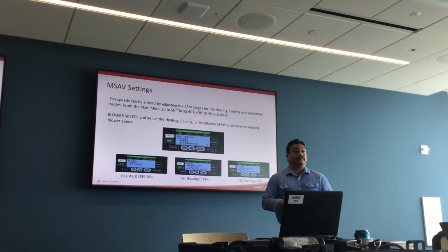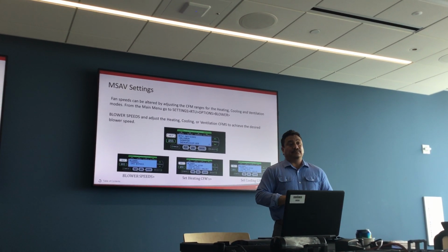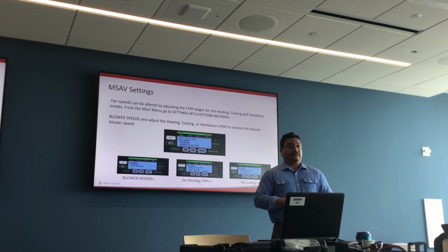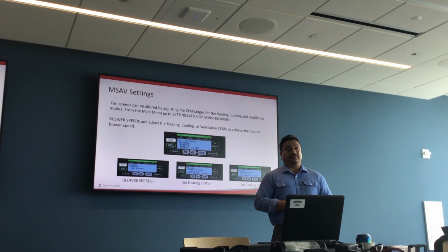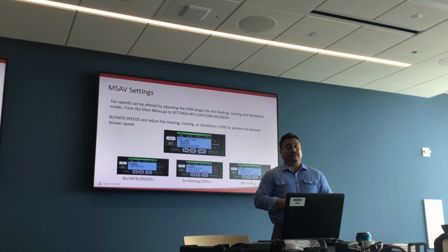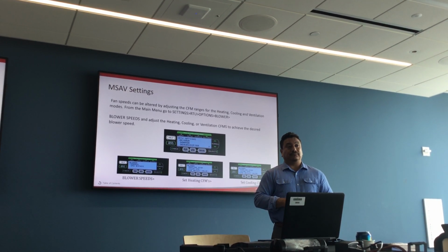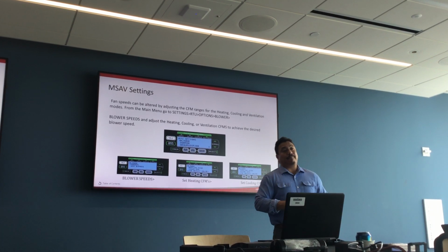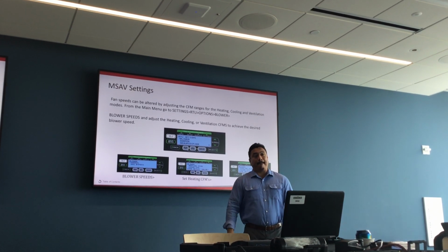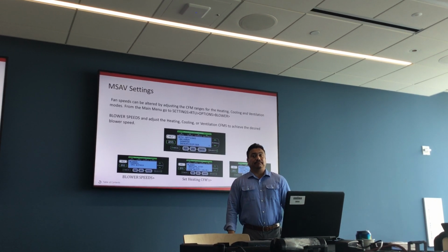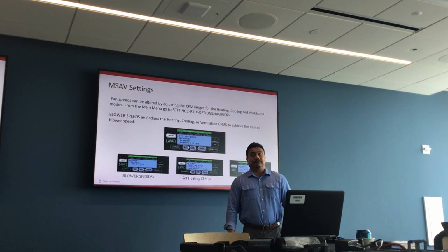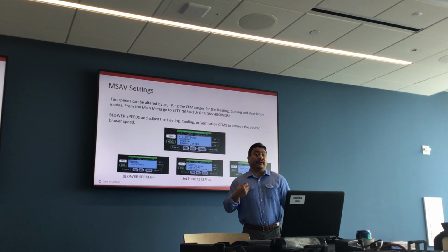It's a mix. What you're saying is, if you see thermostat wires coming up and there's something landed on the occupancy, probably the thermostat is going to be a commercial-grade one with an occupancy setting. Exactly. But if it's some sort of non-commercial thermostat that doesn't even know about occupancy, it won't even have a wire for that, so it has no signal to tell you it's occupied, and you just jumper it right across. So there's either a wire there or it's not. And if the wire isn't there, the unit won't work at all? Well, no, you won't get free cooling, okay?